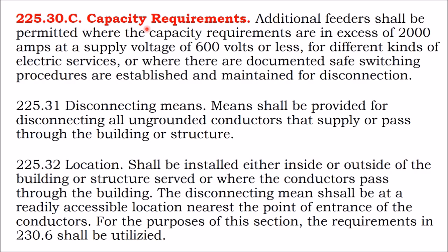So capacity is often referred to as the megawatt rating of the system. In fact, the term capacity factor is a percentage that says what percentage of the year your generator is operating at full capacity. You know, solar being on for 4 to 5 sun hours a day, you're looking at around 1/5 of the hours at most, a sixth to a fifth. So solar capacity factor is 20% at the most, and usually it's more like 15%.